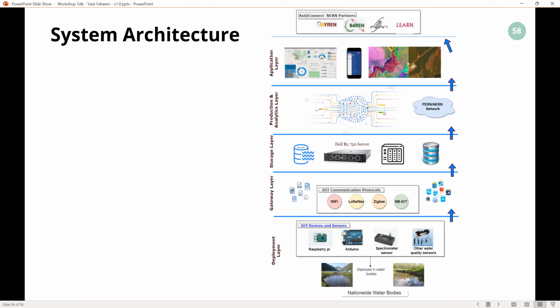Directly to cloud. What is the size of the data and how frequent is this? Basically, we have scalar values reading of, let's say, temperature, the BOD level, TDS level. So the magnitude of data is not that big. That is why I suggested using technologies like LoRaWAN and even SIGFOX that support very low data rates. So that should be sufficient for us.